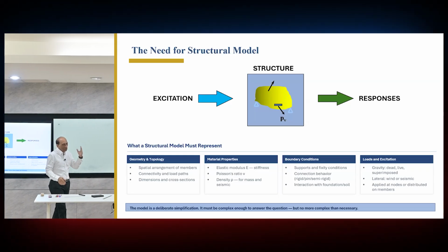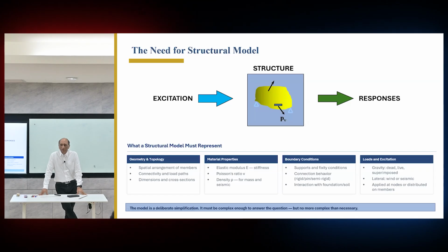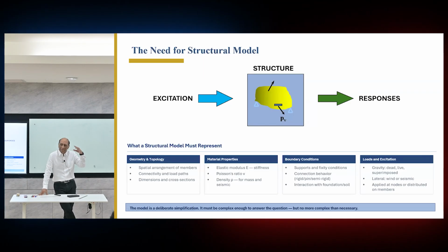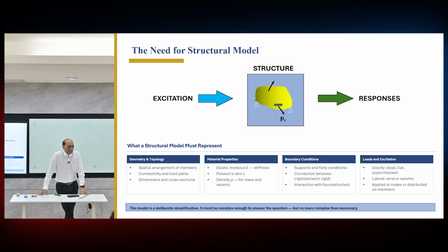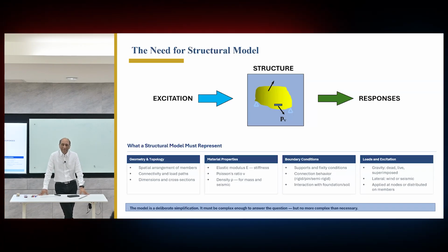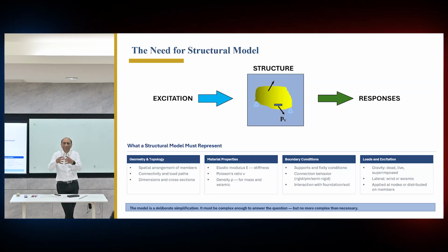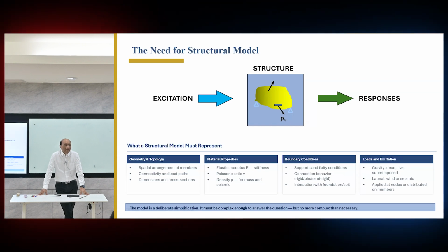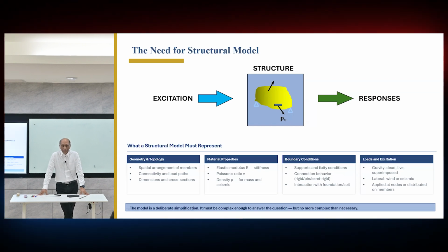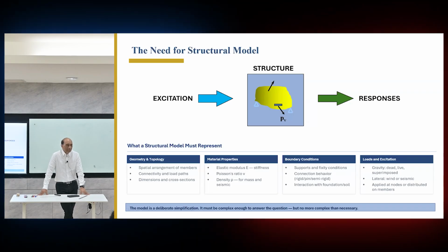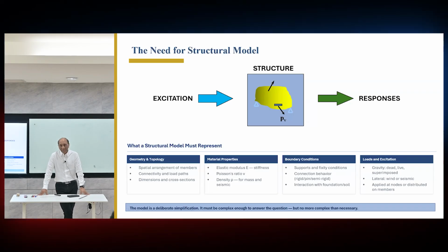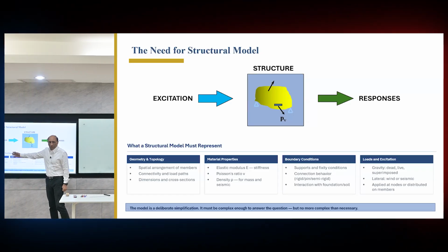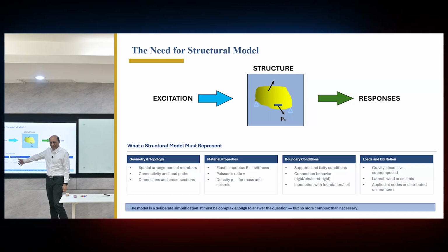Material is another one. We already talked about this in the first course, the complexity of materials, right? So many: isotropic, orthotropic, linear, nonlinear, elastic, inelastic, all kinds of things. But in a program, you may only have an E value to input. So everything will be condensed into an E value for a material. That means material modeling will be the second problem. How much modeling of the material are you going to do? Ductility, confinement, temperature, aging, so many things. Where are you going to draw the line for the materials? So once you make the decision about the geometry, then you have to make the decision about materials.